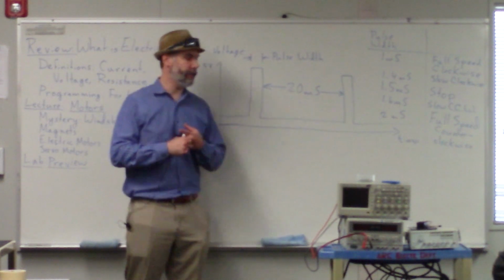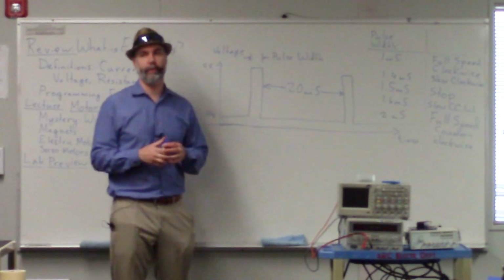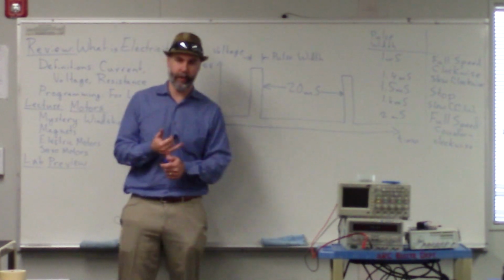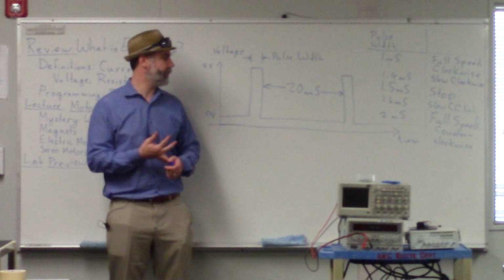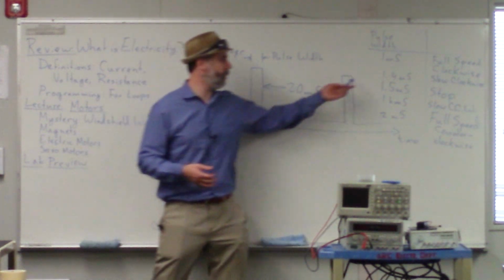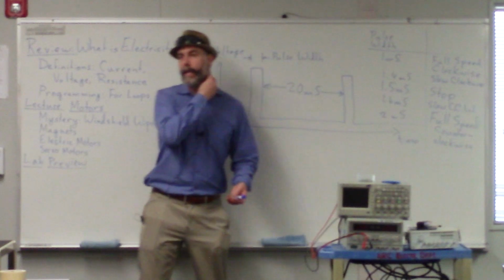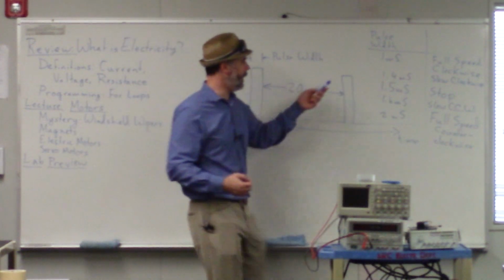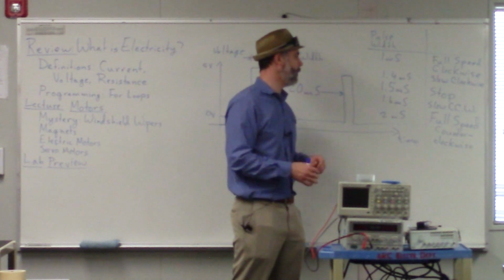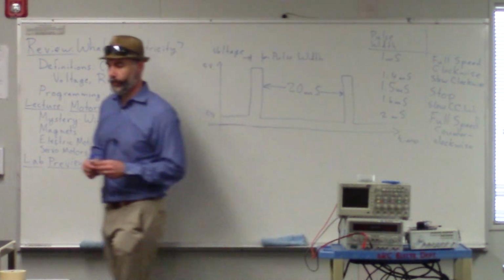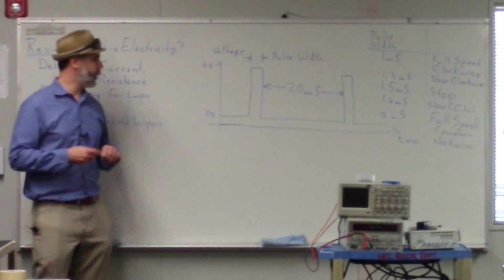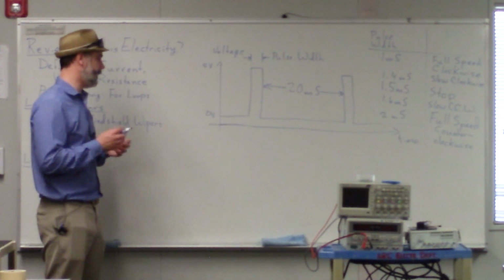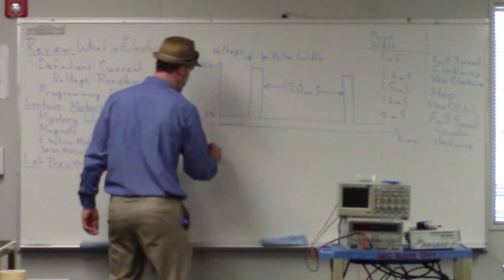But that delay is just not very precise. We can make a delay of 1 millisecond or 2 milliseconds, but we can't really use that delay command to create anything in between those two. So we need a different command to create these pulses. Fortunately, there's a command that does exactly that, and it's called pulse out.